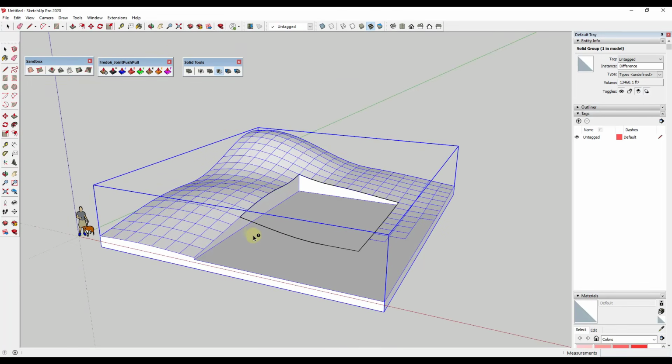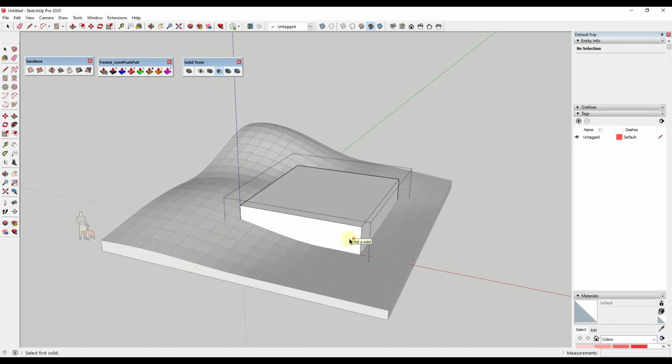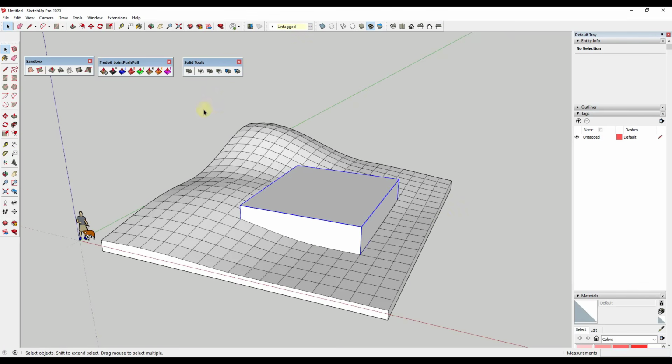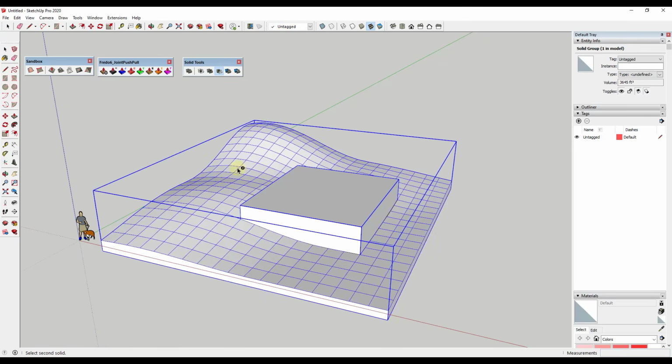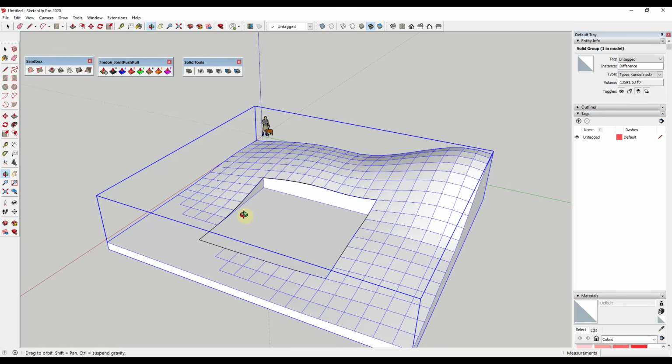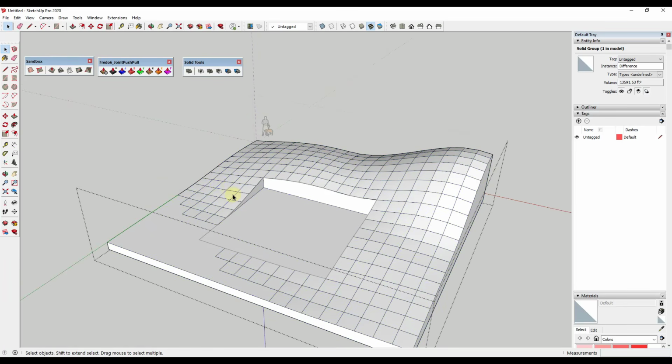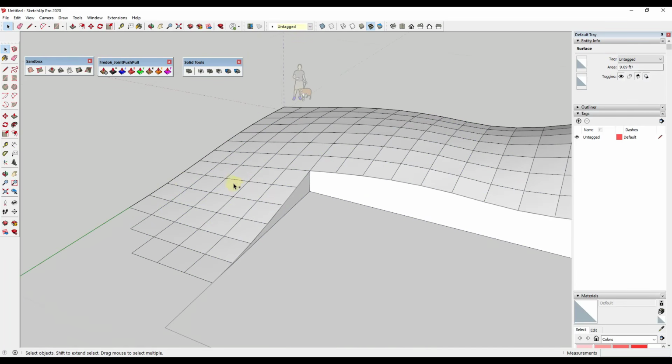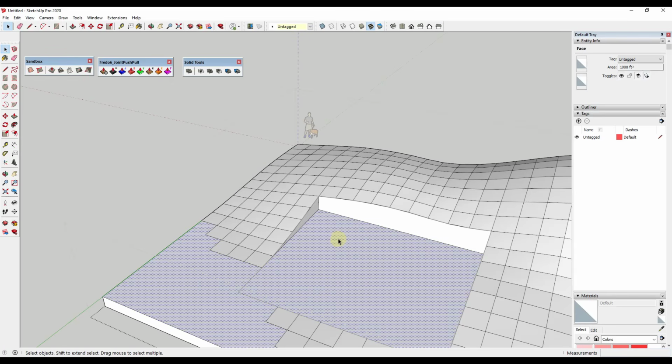That actually gives you this full flat plane. So that's one way to look at this. Another way that we could do this is we could also subtract this and then come in here and fix this manually, right? That's probably not ideal, but you could do that as well. You could come in here maybe with the smooth tool, make your radius way smaller, maybe like 3 or 5 feet, and bring this all down. But again, that gets kind of messy as well.